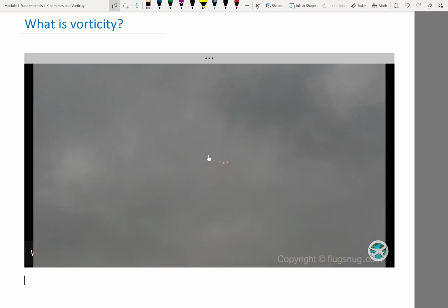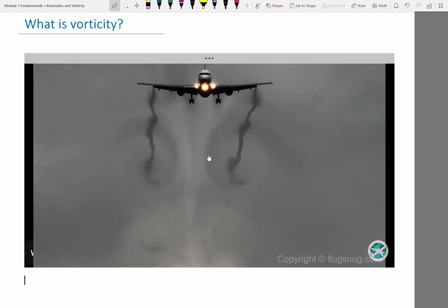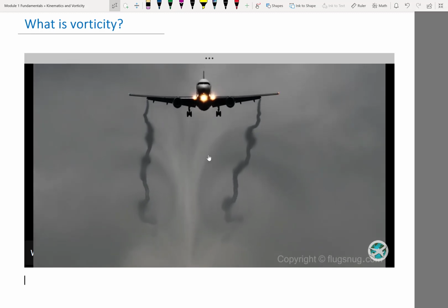And watch how the vorticity, how the vortex moves, and also how the surrounding air moves here where the vortices are. It's maybe hard to see over here, but there are vortices again coming out of the junction between where the flaps are and where there are no flaps. There has to be ailerons right at the end, so you cannot put flaps near the tips. And now you can see very clearly how the air is moving right in between these two vortices.